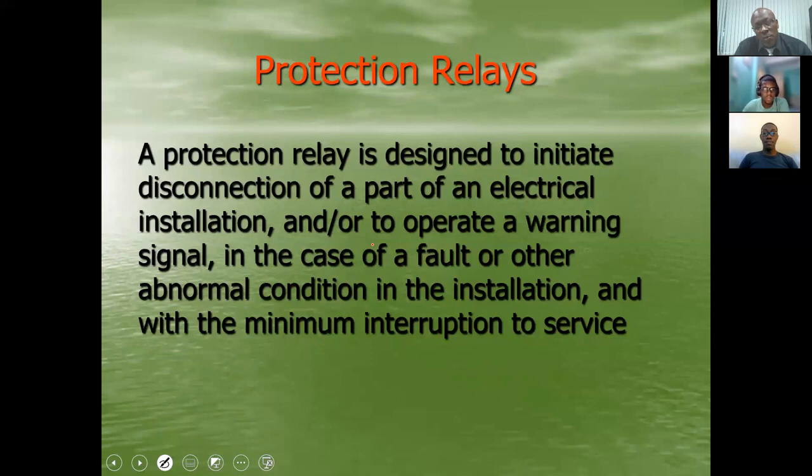So in terms of the warning, as I've said before, sometimes you don't necessarily want to remove the equipment because of the level of disruption that will occur. So for your power transformer, if we think of a relay such as the Buchholz relay, it will send alarms based on the gases that are created within the oil of the transformer.